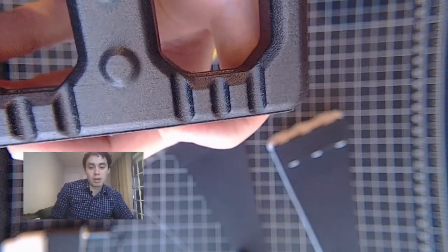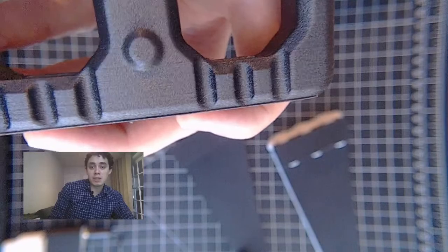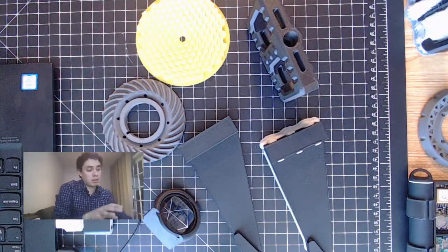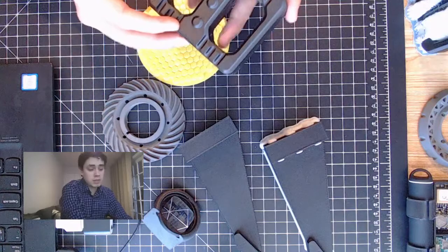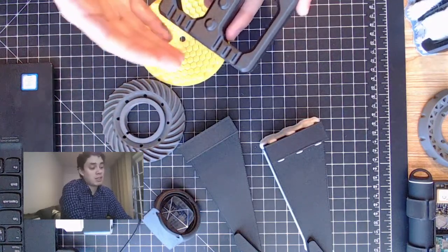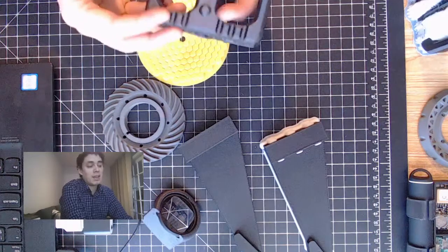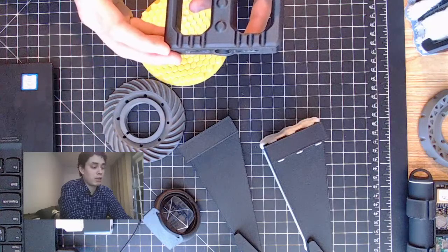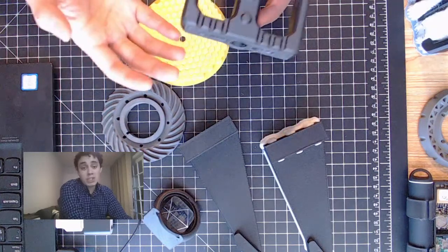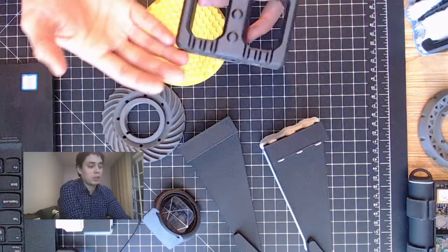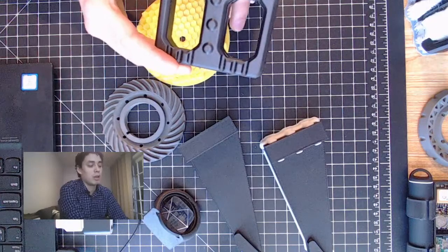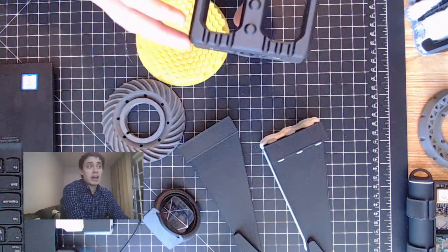as the extruder moves around. What happens when the same object is printed with different orientations? Well, as I said before, you can have many things happen. You can have changes in the look and feel of the object, so the appearance of the object. You can have changes in the performance of the object because the layers will affect the way that an object is able to resist forces being applied to it. And you can have changes in the amount of material and time that it takes to print a particular object, right? An orientation can dramatically affect,